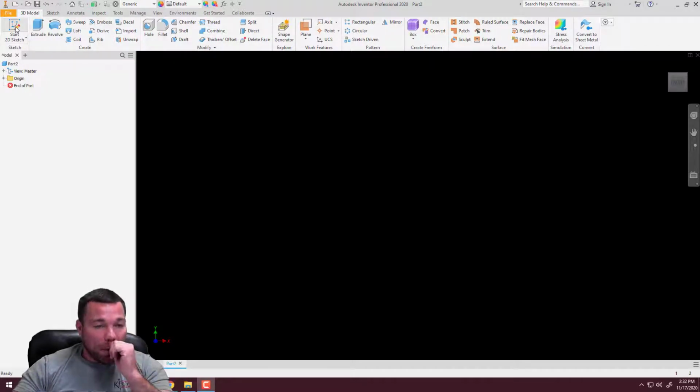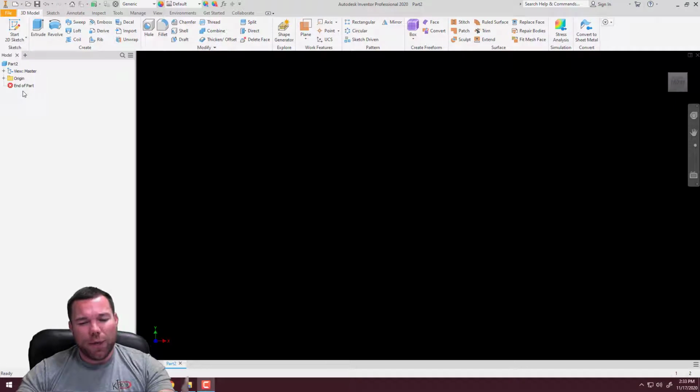Now generally when I create a part, I try to create it with as few operations as possible. So with this one, I'm actually going to be able to create this in 2 operations. If you use a couple more, that's okay. You still have the same result. And it's also okay to have more operations if you have a certain drawing intent. What I mean by that is if you think maybe something might change on the part, and it makes it easier for you to make changes to it by creating separate features, that also makes sense.